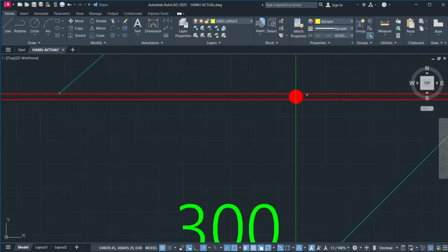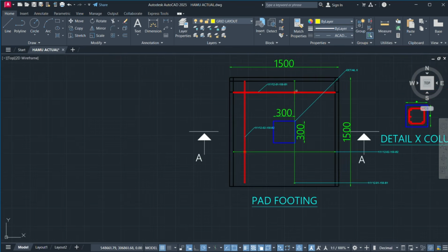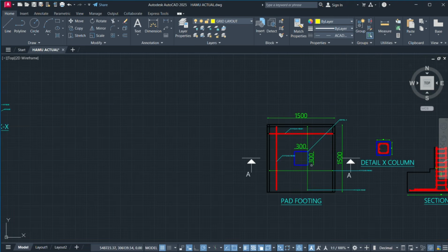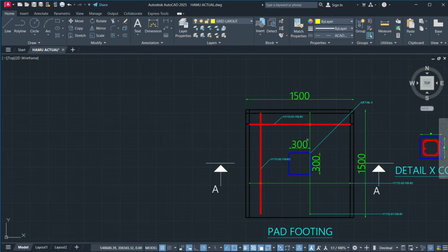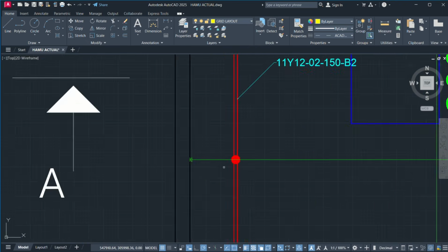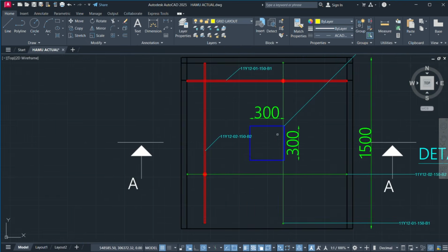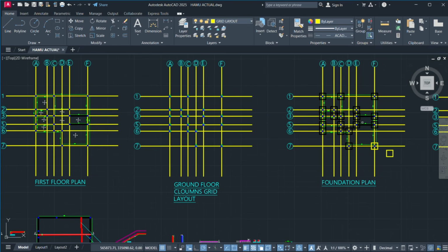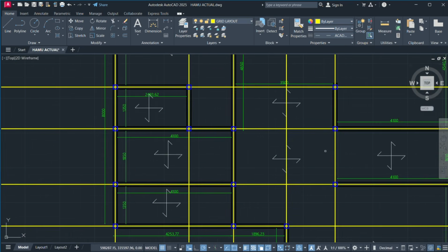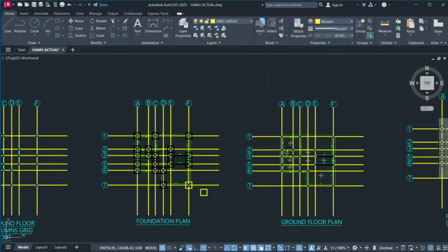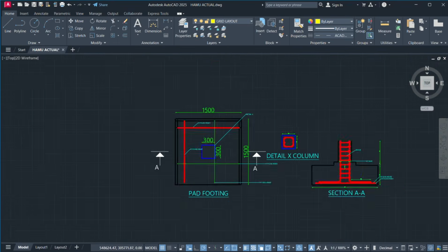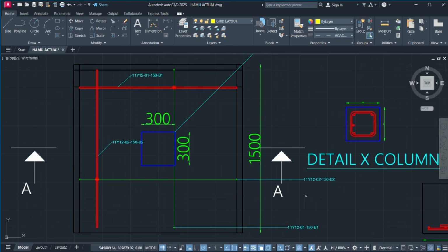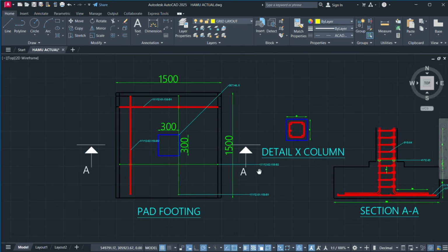Same with this one by a distance of 12. Then you are going to include these points here and include arrows to them like this. Like this. This shows that the rebars are being distributed, and you're going to do it for this same side as well. Then at the middle of all these parts, you're going to put your column which had 300 by 300. Now, here's where you actually show the 300 by 300. Remember what I told you to say that in the plan, you're actually going to do it the way it was for your wall thickness. For example, mine was 150, right? But when you're showing it in this scenario, what's going to happen is that it's going to be a 300 by 300. That's how you're supposed to do it.